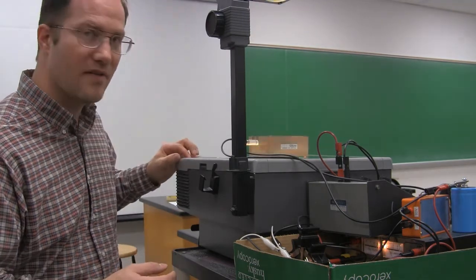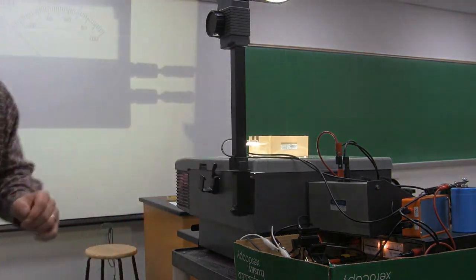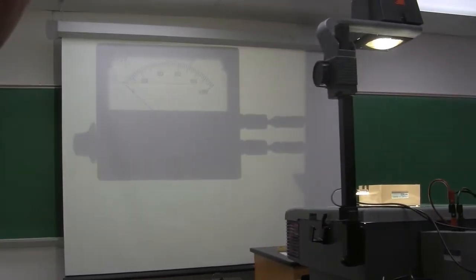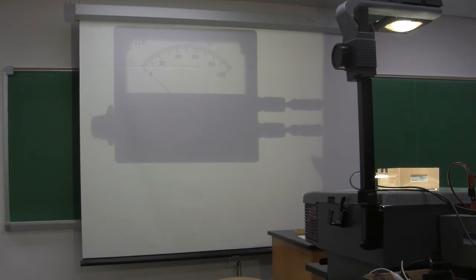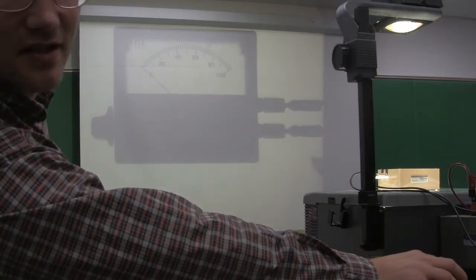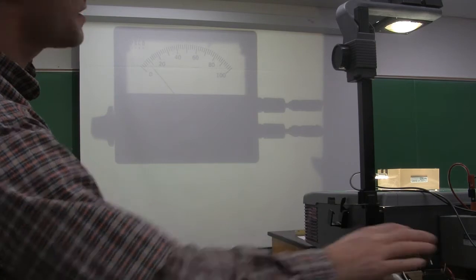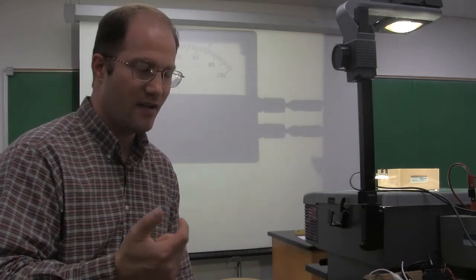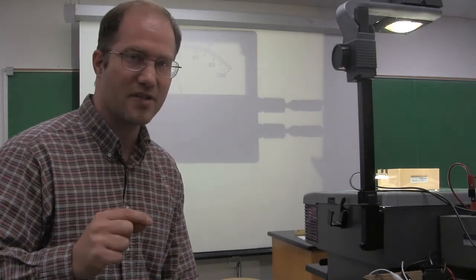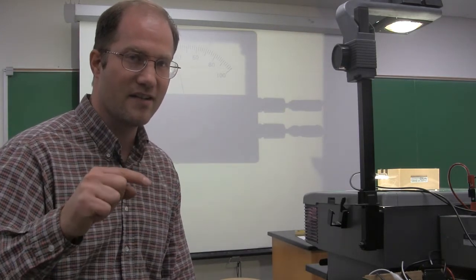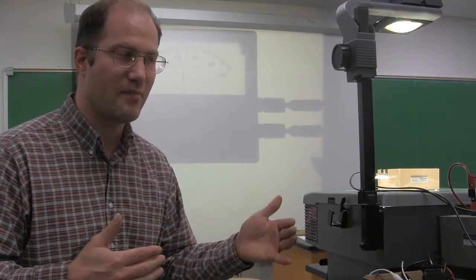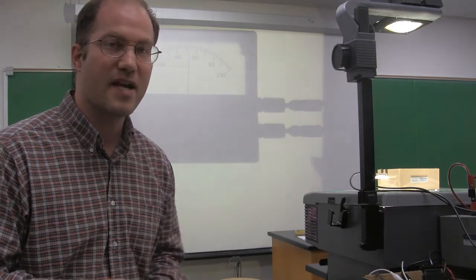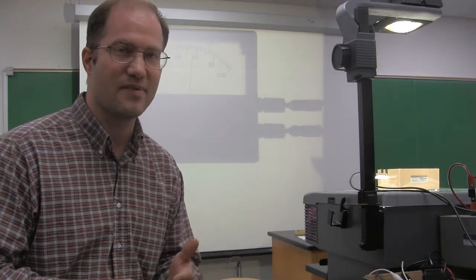So sort of an example of what that looks like. You can see behind me on the board, well, I don't know if you can see it, is the charge and discharge curve. And now as I throw the switch, you can see it beginning to charge. And you see you're in there with your split timer and you're going 10, all right, here's the time at 10, here's the time at 20, here's the time at 30. And it gets slower for each increment of time because it charges more slowly as it finally reaches that maximum voltage of the power supply.